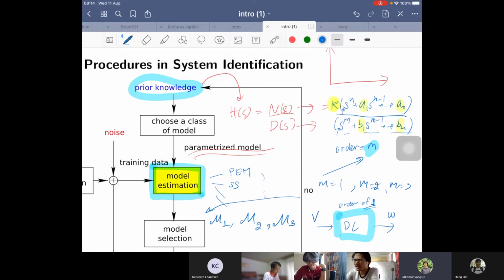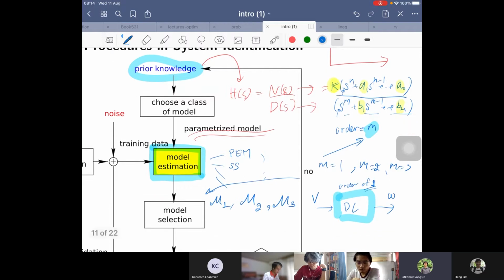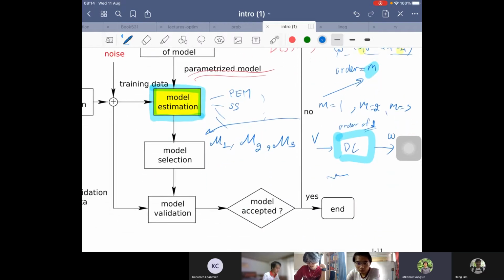We approximate L equal to 0. What are those R and L? That is the armature circuit that connects to the rotor. So you can have a rough idea that if we approximate L as very small, the DC motor is order 1. So maybe order 1 and order 2, right?